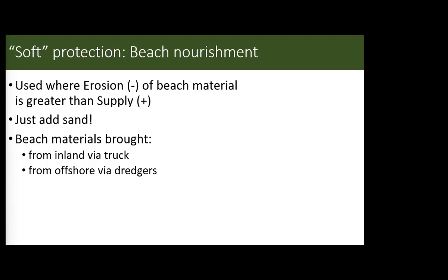So obviously beach nourishment is just bringing in sand from somewhere else and dumping it on the beach. And then obviously you comb it out and do whatever. So you widen that beach surface. So you're basically creating a new source of supply of sediment, which sounds great, doesn't it? Well, it's not. Let me tell you why. So number one, you can't just get any old sand. Remember, sand is a grain size.